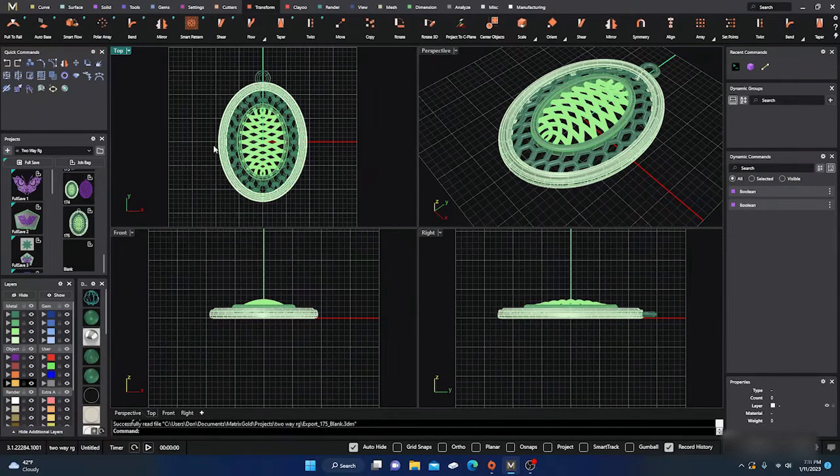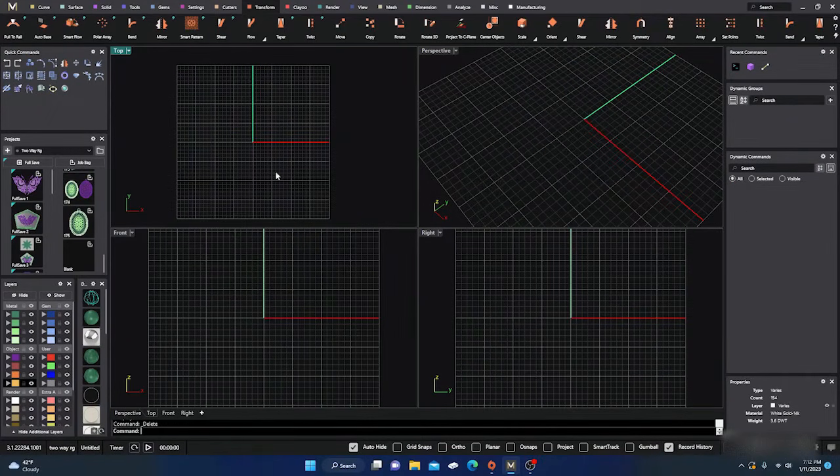And as you're doing it, you can also save full, which will save everything that you've done, all your dynamic commands, all your layers that you've hidden. It'll save everything involved, whereas the job bags will just save certain things, right? So it's important to use these properly.